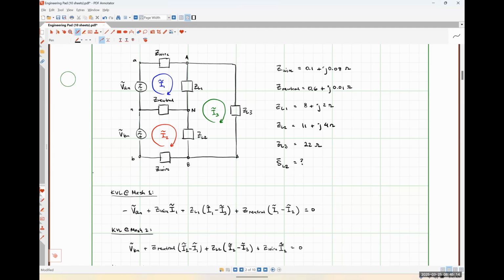So realistically, even though we only have 3 little circuits connected here, so one impedance between A and N, one impedance between B and N, and one impedance between A and B, we could actually use this model to do anything in our home. Because if we had a second circuit connected between A and N, that's just going to be in parallel, and we could lump those 2 impedances together if we were so inclined to find that voltage drop and things like that, right?